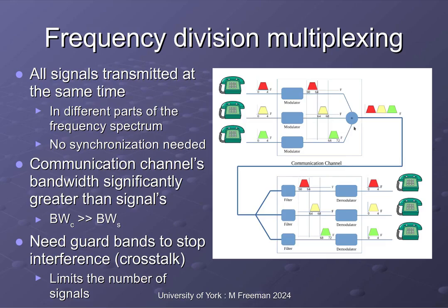We can then add those signals together electronically so they can all be transmitted down the same communication channel at the same time, and when they get to the other end, we can filter out the specific frequencies we're interested in and shift those back down into the audible range so that they'll be received at the telephone at the other end. And that's the way to think about those DSL modems.